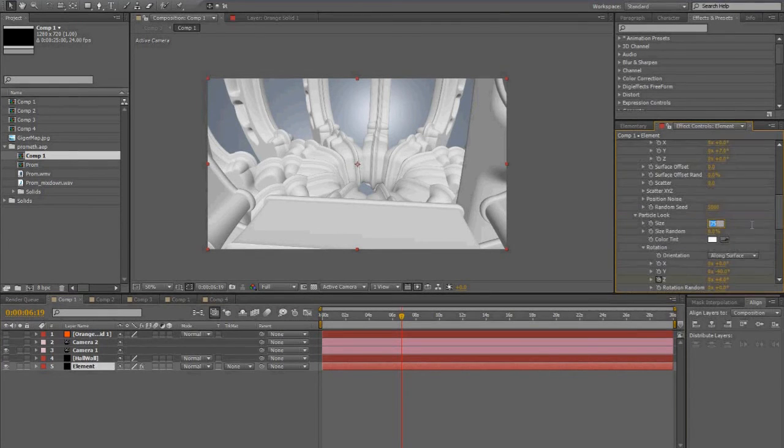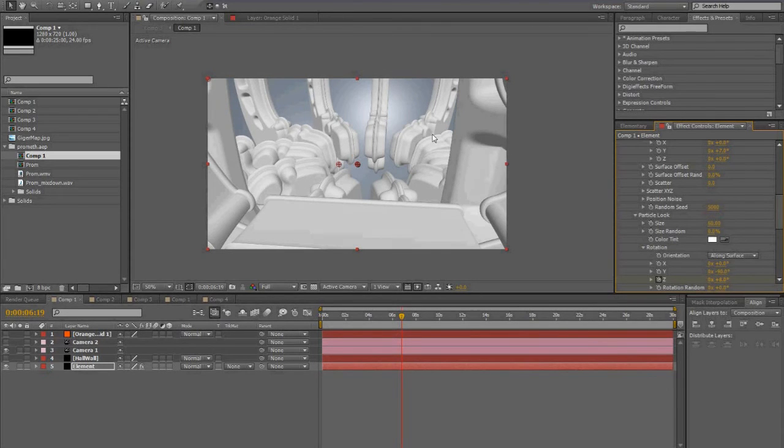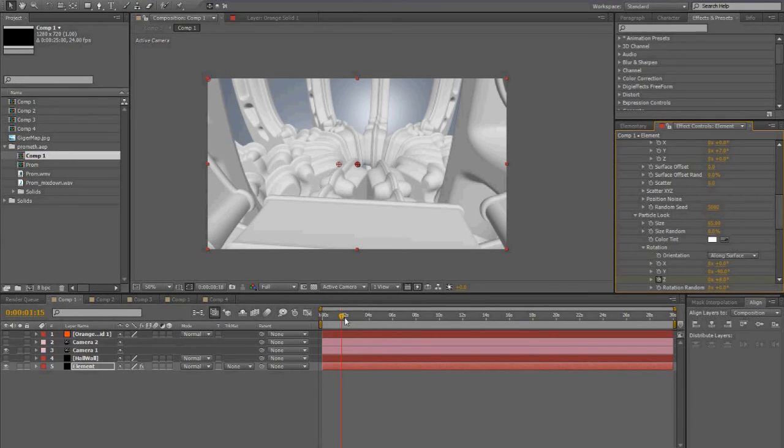Okay, so one thing I do notice a little bit here is the sides clipping through the environment layer, the outer sphere. So you just want to play with the size a little bit. Now 75 was the exact same size as the sphere, but maybe just bring it down a little bit in size so it's not clipping so badly when the sphere opens up, or when those ribs move. So you can see that's looking a little bit better. It's not clipping anymore.